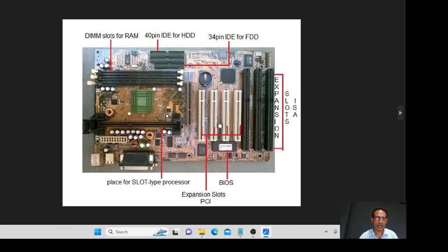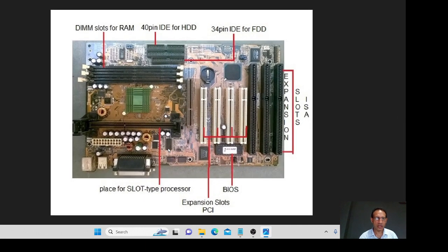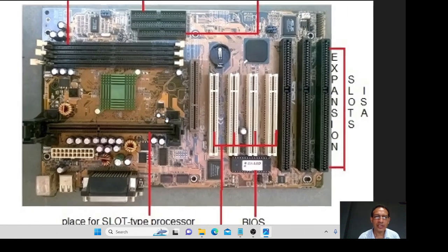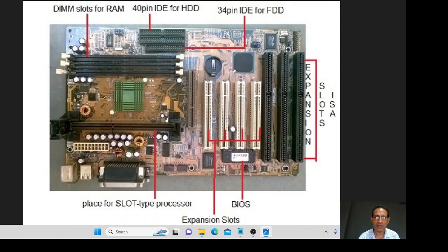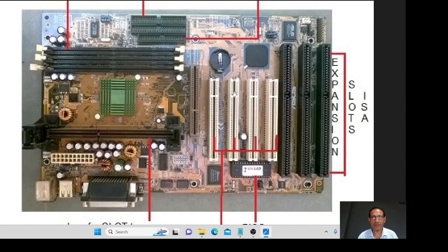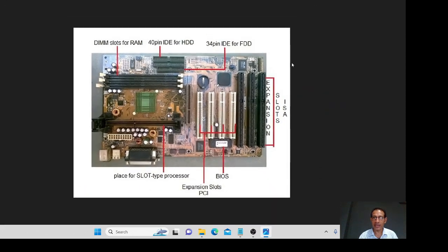Here's another type, an older type of ATX motherboard, because it has ISA also, and PCI and AGP, as well as the RAM slots here, the DIMMs for RAM, and AGP here. So roughly, the CMOS battery, and from here the processor, yes, it's inside here, the processor. And the north bridge and the south bridge can look like this, right? ATX, the older type.